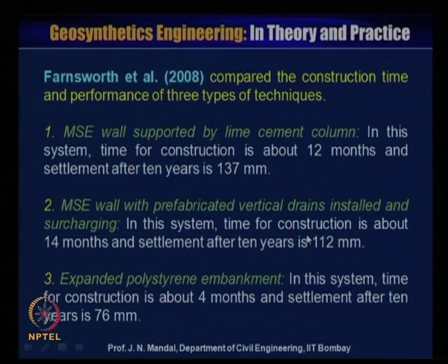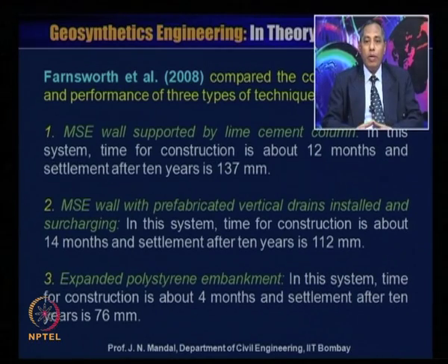Farnsworth et al. 2008 compared the construction time and performance of three types of techniques. One, MSE or mechanically stabilized earth wall supported by lime cement columns. In this system, the time for construction is about 12 months and settlement after 10 years is 137 millimeter.